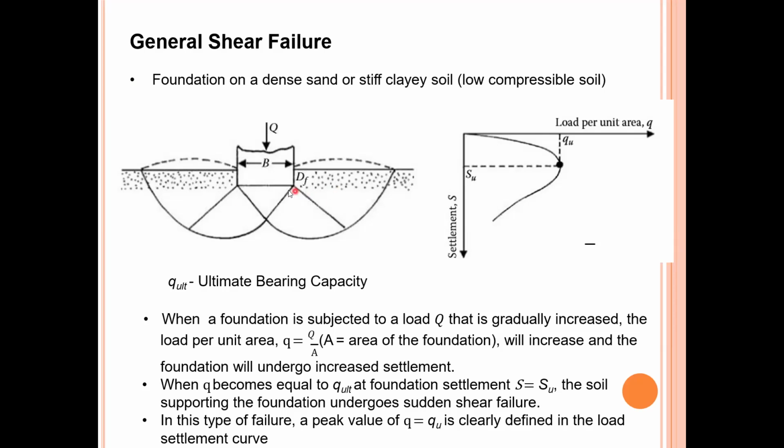So you can see when we keep applying the load, our foundation settles downward. And with that downward movement, this area compresses and this area is subjected to tension. What you have to understand is that in this type of failure, a peak value is clearly defined.